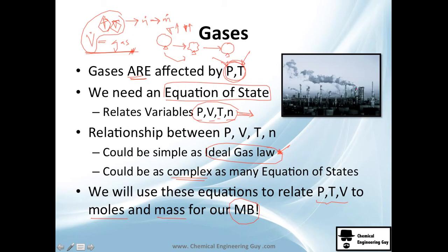So imagine I told you this place right here has a volumetric flow of this gas, I don't know which gas, of 10 cubic meters per hour. So essentially you want to know, for mass balance purposes, how much mass is there. So you will need to ask what's the temperature, what's the pressure, what's the composition, and you will be able to calculate eventually the mass being lost by this gas. And as you can see, it's a lot of gas. So if you don't account for this gas, you will have no right mass balance in this plant.